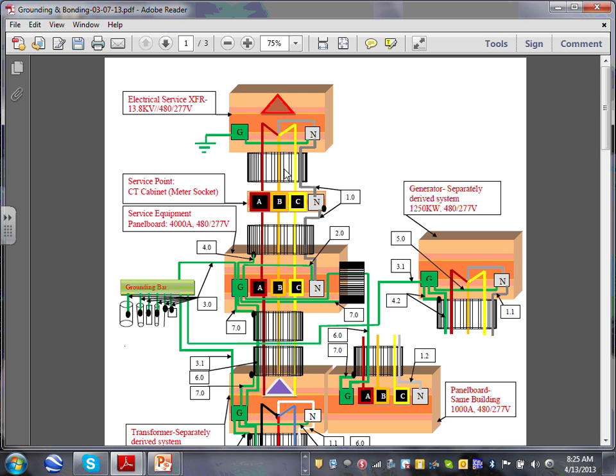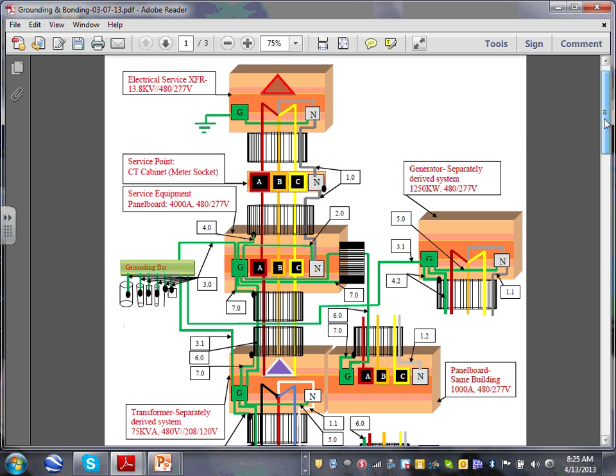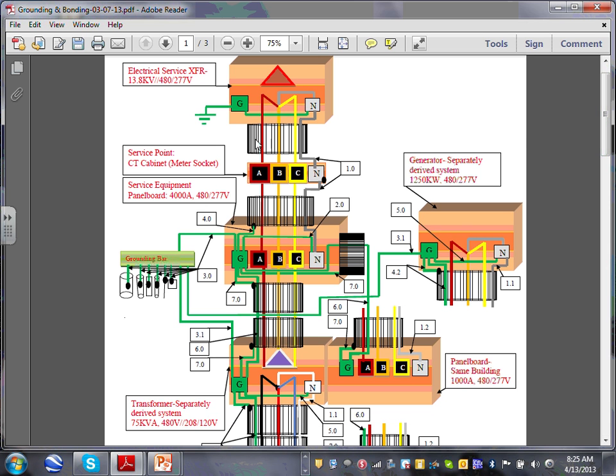And to your building, it comes with these shaded things here, supposed to be conduits. Again, I'm not a graphic designer. I did as much as I could, guys. So that's supposed to be a conduit. For us, really it starts with a conduit coming from the secondary of the transformer, as you can see, into the so-called service point, which is the CT cabinet or the meter socket. Or if you are doing residential, it will be at the top of the mast where you tie to your overhead conductors coming.